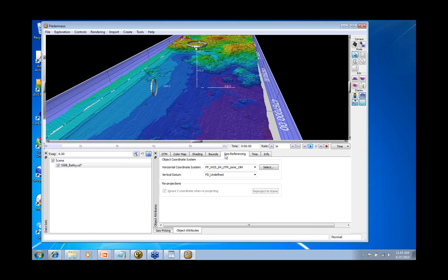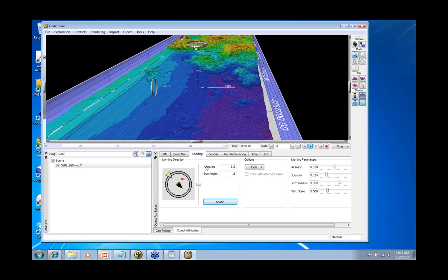My question is, when we import the bathymetry data into Fledermaus and we see it in color format, is it possible to know the sun illumination angle? If I'm going to shading, the azimuth is the angle. And for this one, the start angle, the 0 degree starts from where? Because it normally differs from software to software. I believe 0 is at north there. So as you go around the circle up to 360.